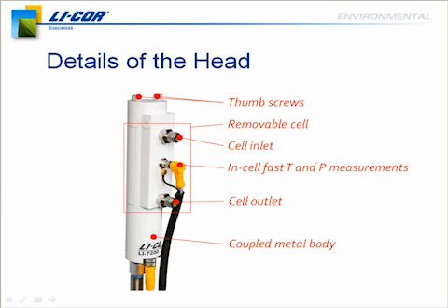And there's some benefits to not even having the filter. One of those is that you don't have the attenuation of H2O that sometimes happens when you get water vapor trapped in the filter. In addition, filters can create resistance to the flow. And if you have that resistance, then you're going to have a larger pressure drop, which again comes back to the point that you need a larger pump, which would require more power. So having this open system without a filter that doesn't contaminate easily is a real benefit.